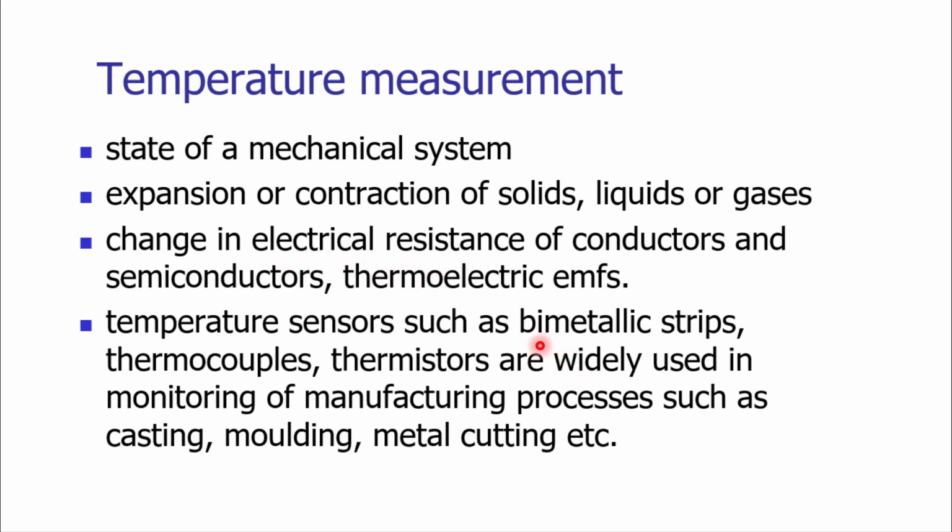The temperatures are not only affecting the dimensions of the materials, the temperatures are affecting their electrical resistance as well. In general, various sensors such as bimetallic strips for alarms, thermocouples to measure the temperature of various components of machine tools, and thermistors are used. Various operations which we have seen in our previous lectures such as casting, molding and metal cutting, in all these applications we need the measurement of temperature. Now let us look at the construction and working of some of the important temperature measurement sensors.